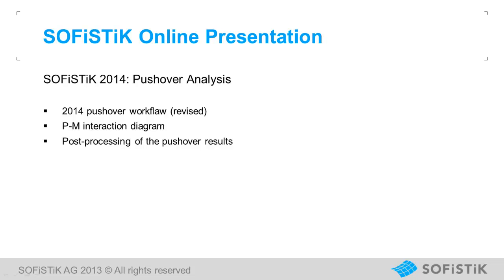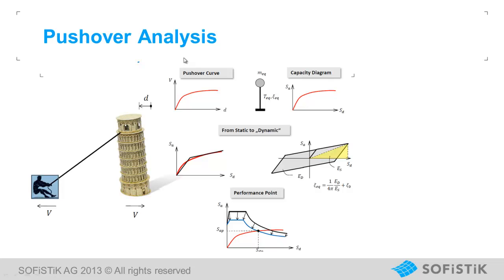This video covers the following topics regarding pushover analysis: the revision of the workflow for implementing pushover analysis into SOFiSTiK, the possibility of an axial force moment interaction diagram definition for the implicit hinges, and the improved visualization of results concerning pushover analysis. At this slide, we see a simplified explanation of the pushover analysis method according to the ATC40.